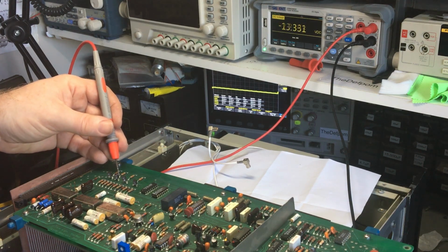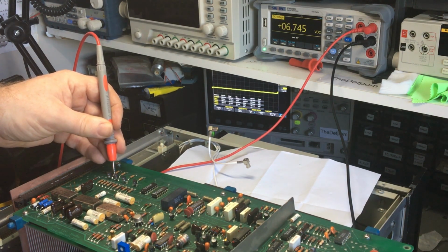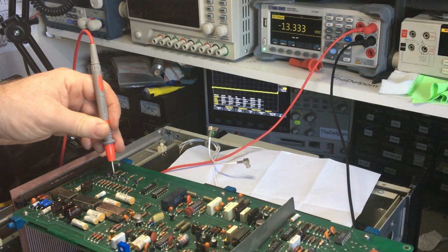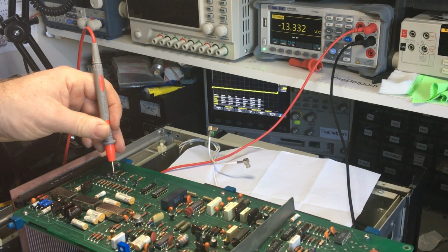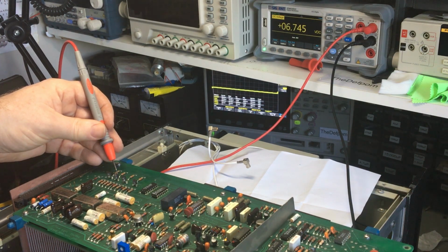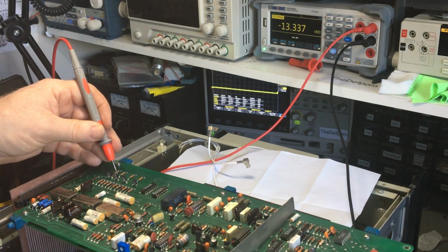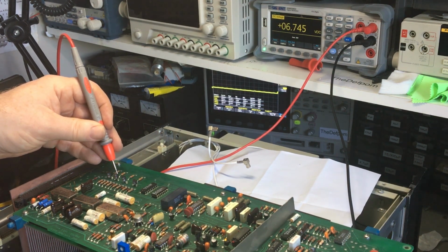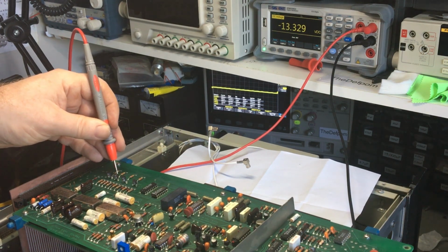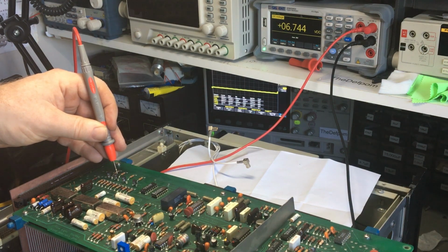So measure the next one. So this one here, Q16, is only on, no, only off. I'm measuring here. I must be in the wrong place. No, that's the right one. So 100 hertz, 10 hertz, 1 kilohertz. It changes. The other zones it stays on. Now let's check that. It's off. It'll pull up when it's on. So it's only on 1 kilohertz. 10 kilohertz. Sorry, it's 10 kilohertz. Only on at 10 kilohertz.